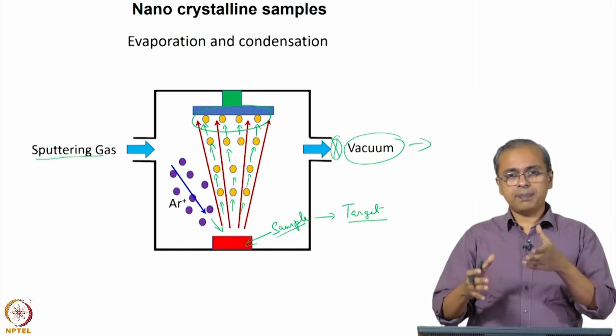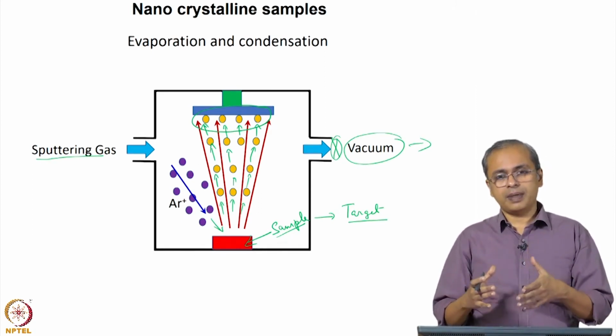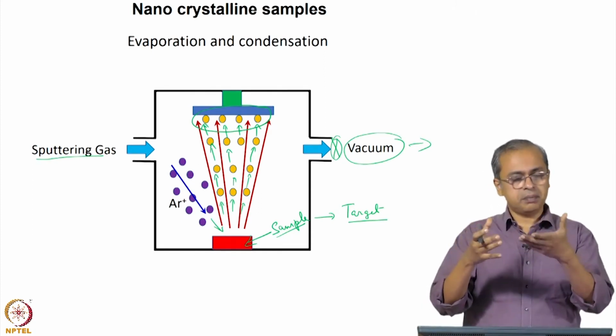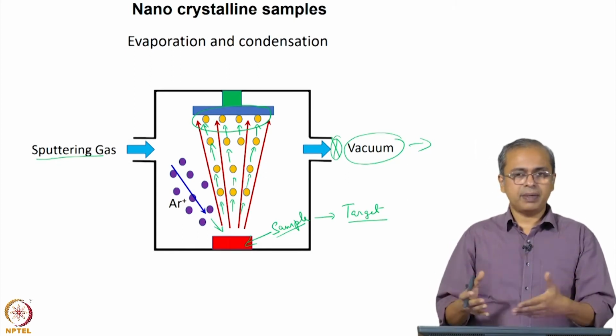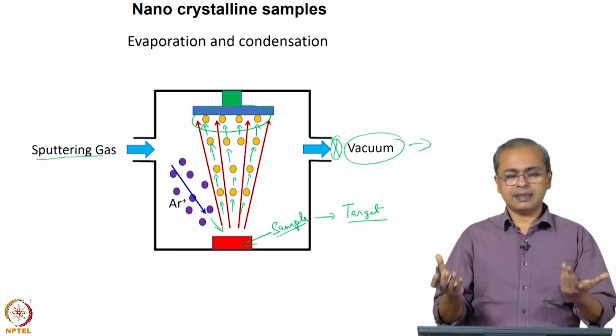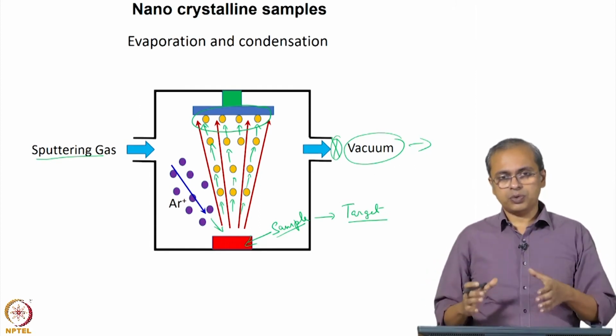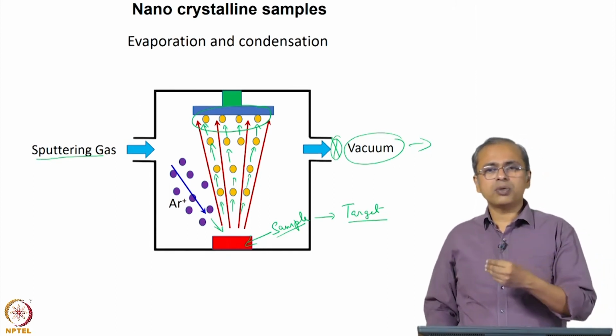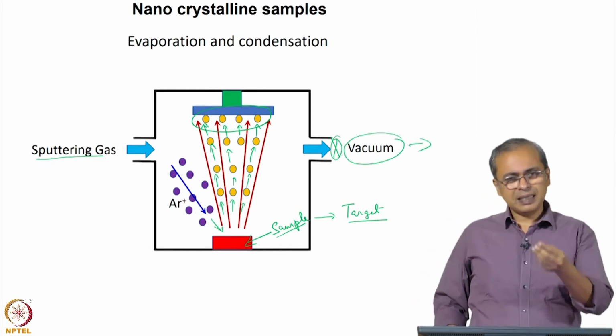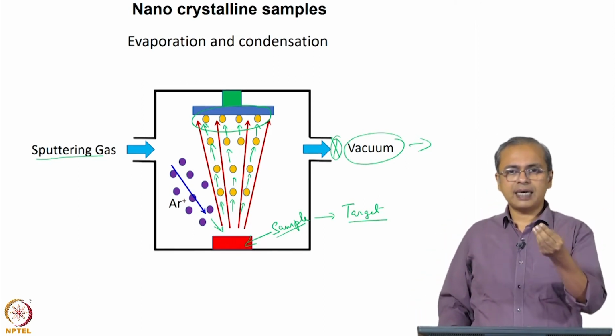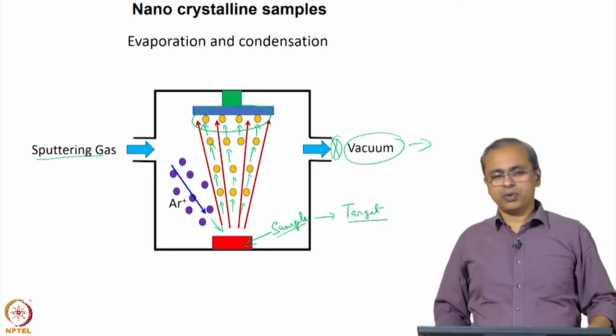They will sell separately, they will sell high quality maybe platinum target, palladium target, copper target, etc. They will sell that to you, and that is the kind of target that you will use. So you actually do not evaporate the entire target, you are basically removing only a few microns of the target and then you make it settle on your sample.